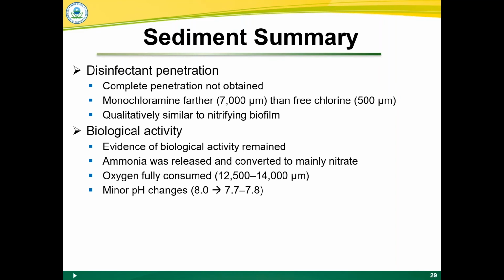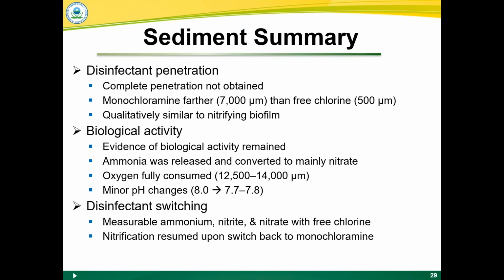So we go through the whole oxygen conditions, where you have aerobic towards the surface, the upper part of the sediment, go to anoxic about midway through the sediment, and then we would have had anaerobic at the bottom of the sediment. The disinfection switching, again, we still had measurable nitrogen species in the sediment the entire time we were on the free chlorine, and we did get nitrification to resume right when we switched back to monochloramine. Again, bottom line, if you take nothing else away from this, it's a good idea to get the sediments out of your system.